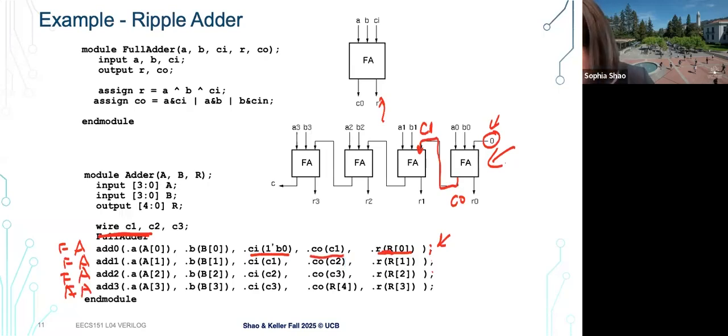And if we look at the carry in of the next one, those two are being connected because the carry from the previous adder is being propagated to the input carry, right? So you can see this connection, and that's why we need to use those wires here. Those are internal wires that exist in my circuit, but are not input and output signals.